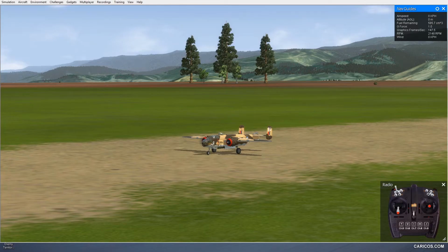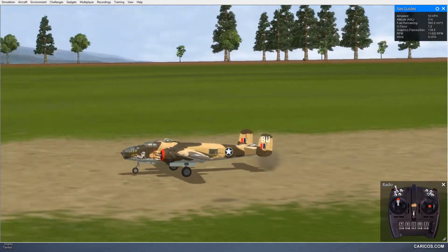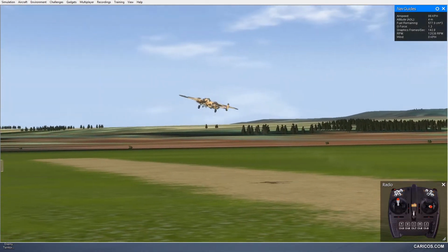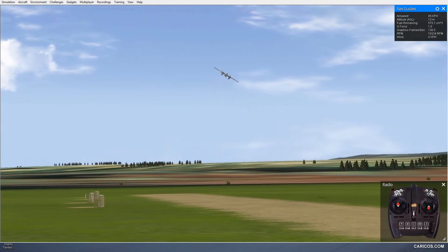We're going to take off and start that initial landing sequence of events that I typically perform every time I land my radio controlled airplanes. The first thing I'm going to do is give myself some half flaps so that we can take off. I'm going to apply full throttle here. The plane pretty well gets itself off the air. I'm going to pick the gear up and reduce throttle a little bit.